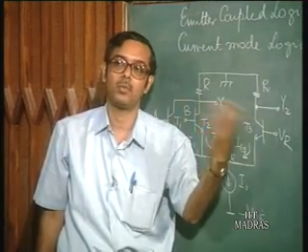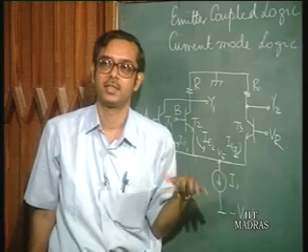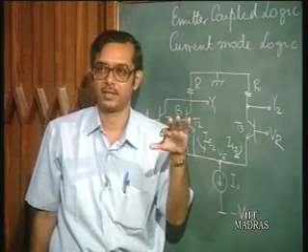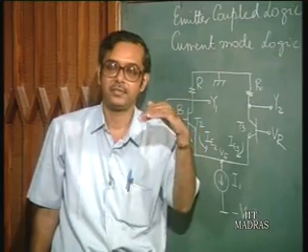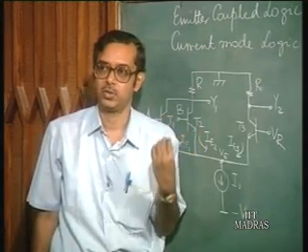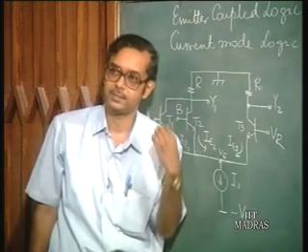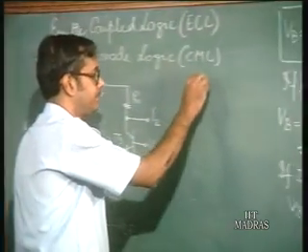So the important thing here is you require just a very small voltage variation to change the state of the logic, which is very important because that gives us very high speed, and that is a direct result of the exponential dependence of current on voltage. In MOS circuits you would require a large voltage variation to change the logic. Here you require a very small voltage variation, and small voltage variation requires less time, so you get high speed. All these things are related.